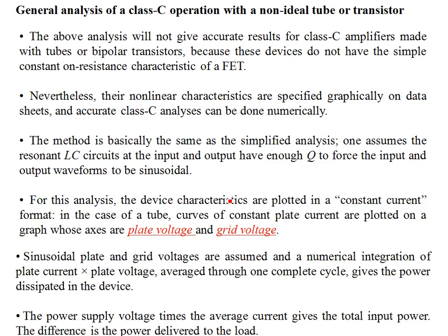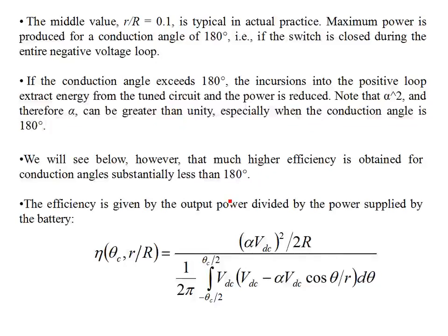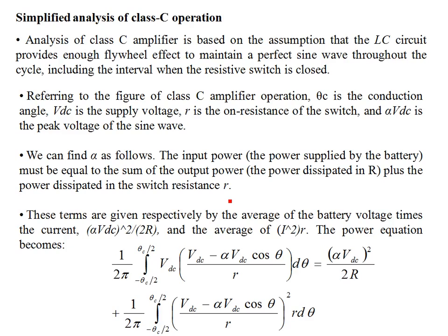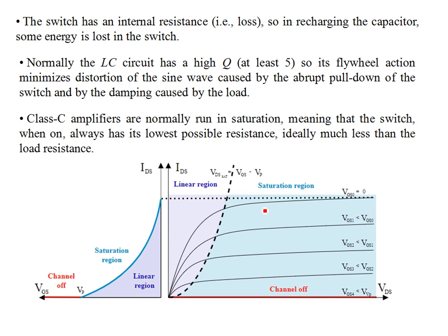But again, the analysis assumed an FET as an active device, and I told you that we were operating this as a switch in the saturation region where the current is not affected by the drain source supply, but only by the VGS, the gate source voltage. So as you decrease VGS, it becomes more and more negative, and you can drive the transistor into the cutoff region.